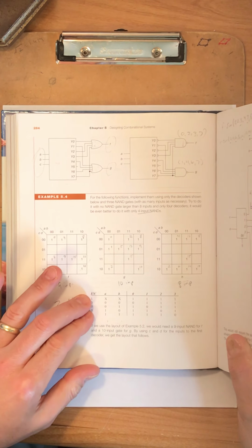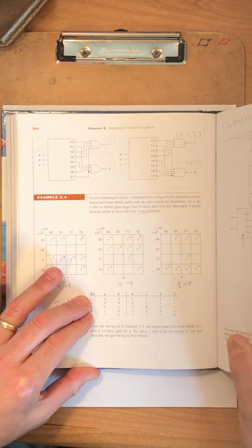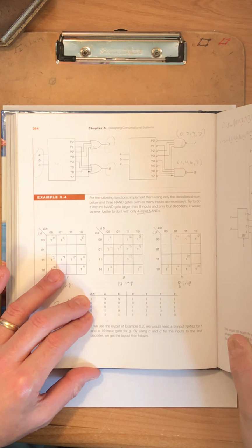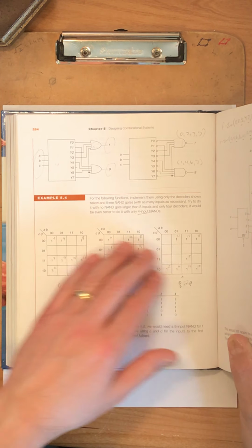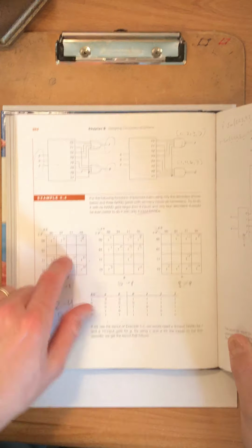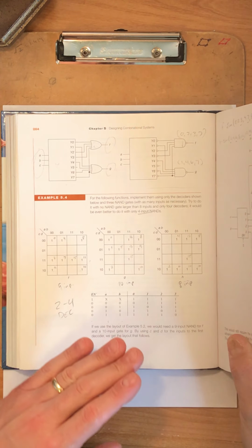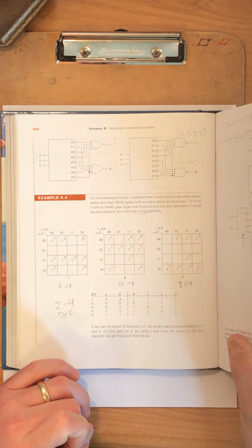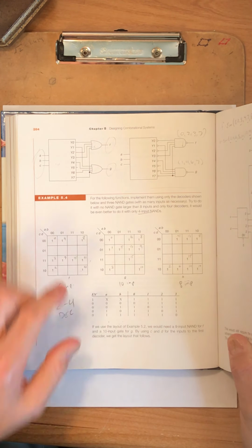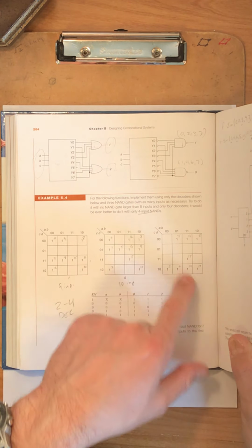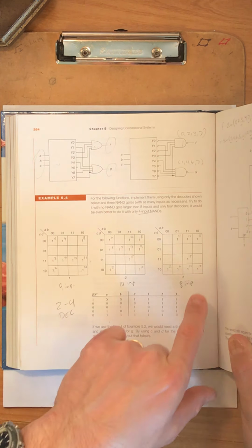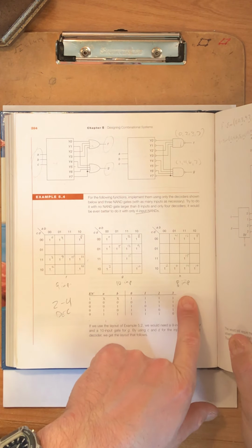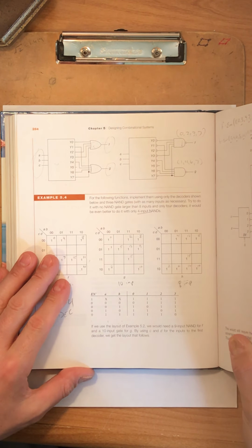We could take this decoder and build a 4 to 16 decoder, because we have 16 different possible minterms up here. So we need a 4 to 16 decoder, and then simply use NAND gates and take all the individual minterms, which you can see I've numbered in my book. We need a 9 input NAND gate here, a 10 input NAND gate here, and an 8 input NAND gate here. So that's one way to do that.